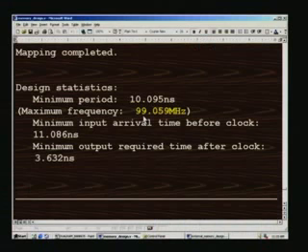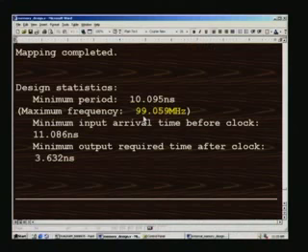So, 40,000 into 5, that is 200,000 transistors. What crosses 50,000 is categorized as VLSI, and that is how it is. And the maximum frequency of operation is 99 megahertz. We are just falling short of the magical figure of 100 megahertz, right. Thank you.